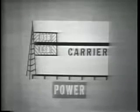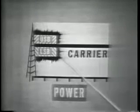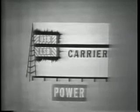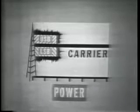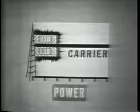Thus, the sidebands are being deprived of power which might increase the range of transmission. And also, since we have two sidebands, the required receiver bandwidth allows in more atmospheric noise at the received end. Noise, of course, is proportional to bandwidth. Thus, the wider bandwidth raises the noise level of the signal. If the signal is very weak, it may be lost in the noise and thus be totally unusable.